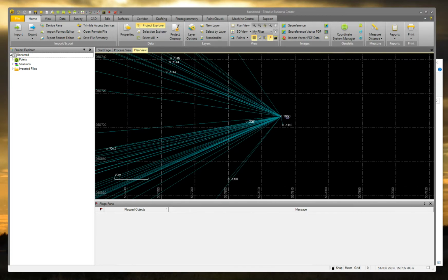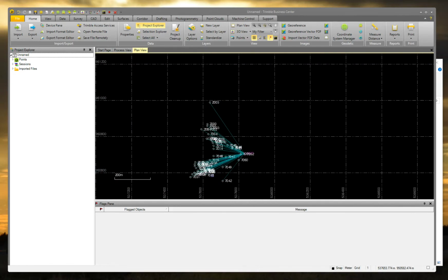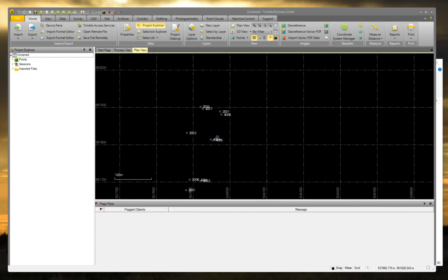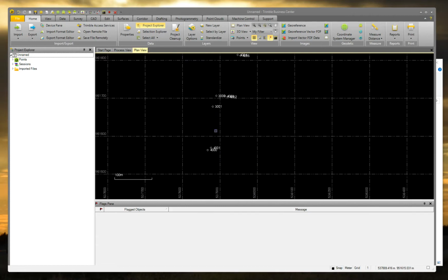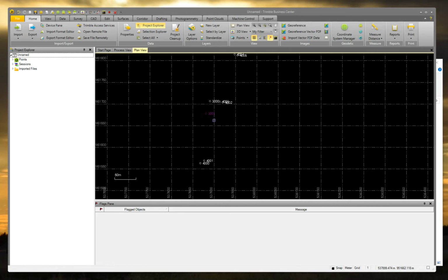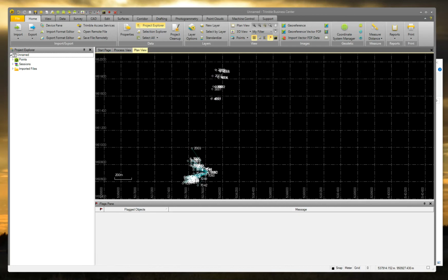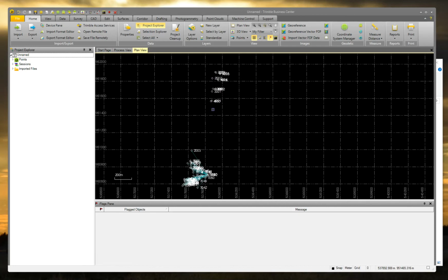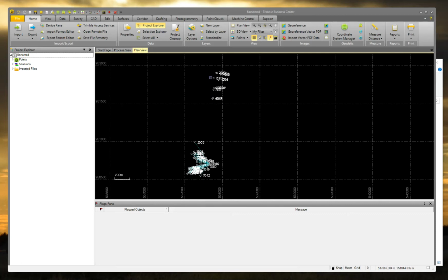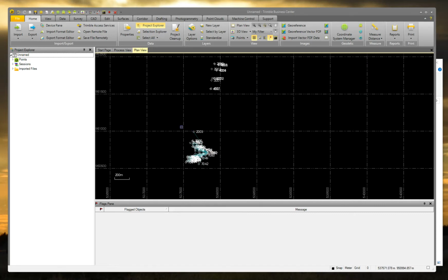So here we have the first day of data. You got 1,000 point, a few GPS shots. Also got some stuff out here I don't understand. Looks like maybe the base shut down or something weird happened here, because you've got points out there, but you don't have vectors, which indicates that the rover was running and the base wasn't. So we should have lines out to there.